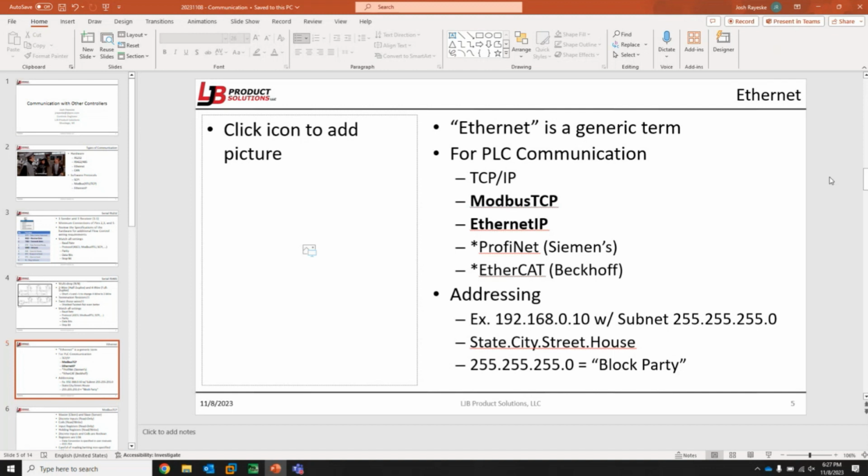The other catch is the EtherCAT expansion chassis are only able to communicate through an EtherCAT port to the expansion chassis. So don't make the mistake of buying some peripheral with EtherCAT and expect the RT chassis with EtherCAT to communicate with it. There's no API, I believe, in LabVIEW. It may have changed. I know that was a few years ago when I made that request, but EtherCAT is strictly for communicating with an expansion chassis.